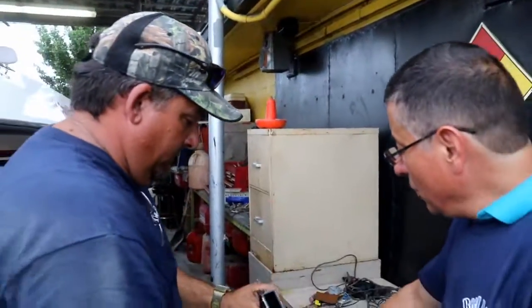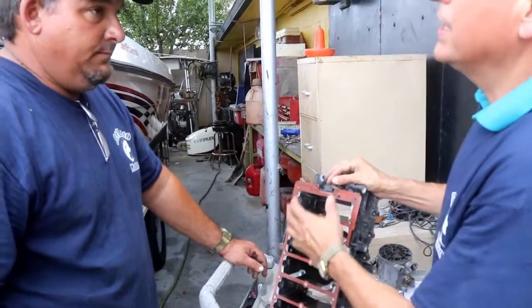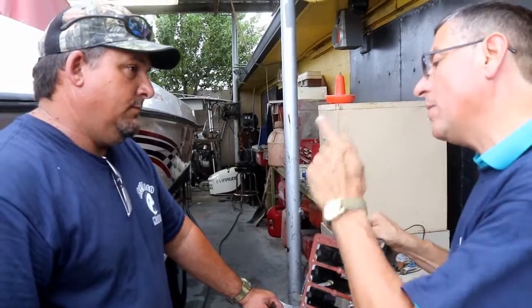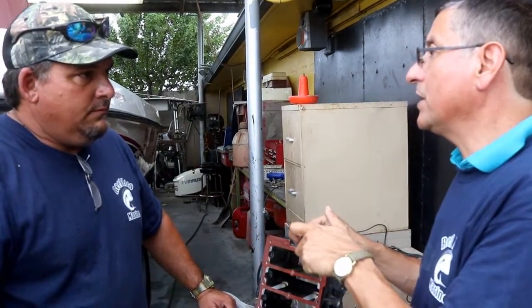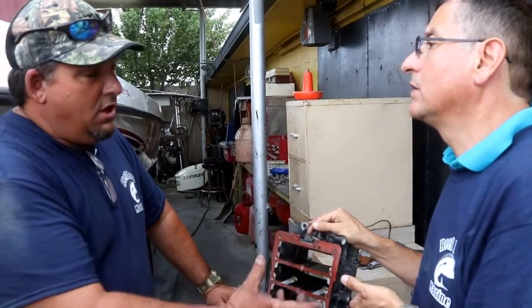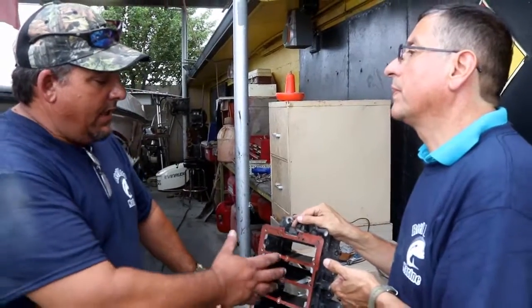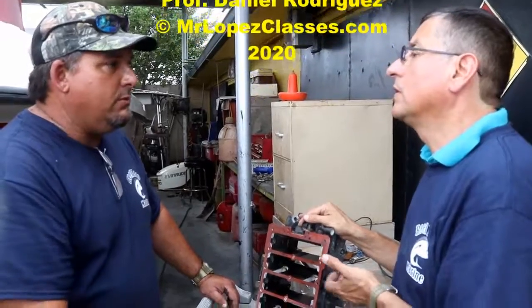Danny, in other words, I have one per each cylinder. Correct. And if I have low compression in one particular cylinder, this is a possibility. It could be one of the possibilities. The other ones could be the head, the rings, the pistons. But this is one of the possibilities. The enemy is the water, and any debris. Like if there's a catastrophic failure, usually metal comes out and will damage the reed valve. Anytime you have a catastrophic failure in a cylinder, you have to replace the reed valves. We don't even rebuild them; we just replace them with brand new ones. Correct.